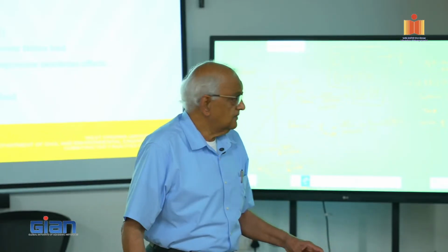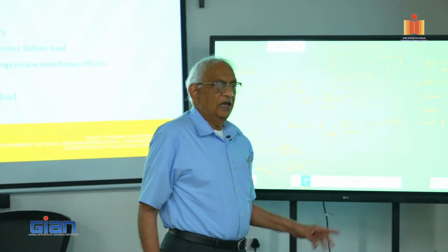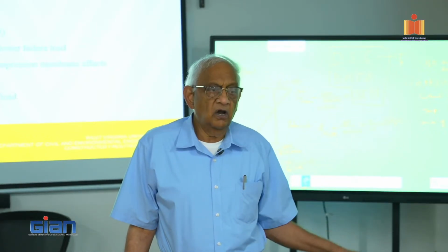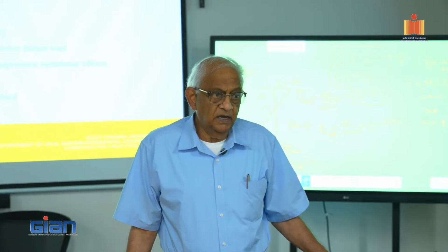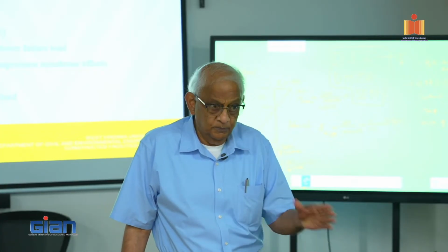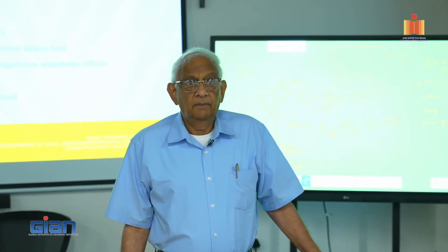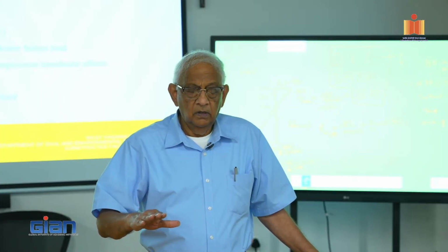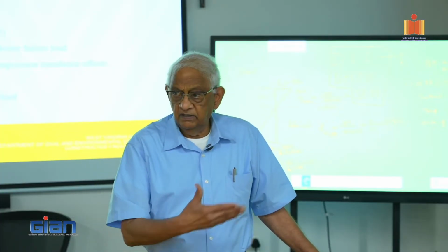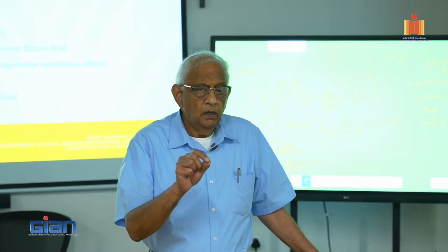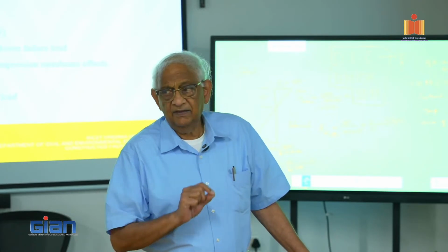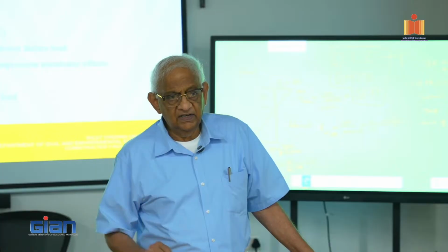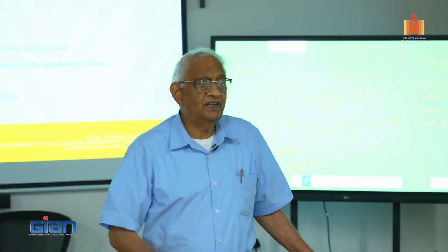Now, let's go to SEM, scanning. I won't go into CAT scans and other things, they're all equally important. But if you talk about scanning electron microscope, now we are having such powerful microscopes that you cut a cross section, you prepare the surface, you put it under the microscope. Glass will give you one color, resin will give you another color, filler will give you a third color, void will give you a fourth.